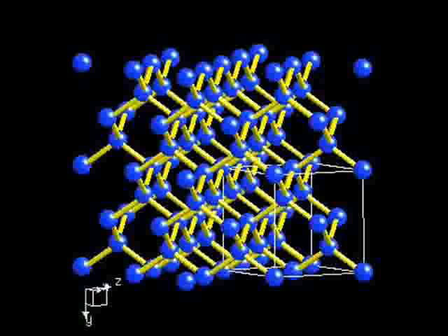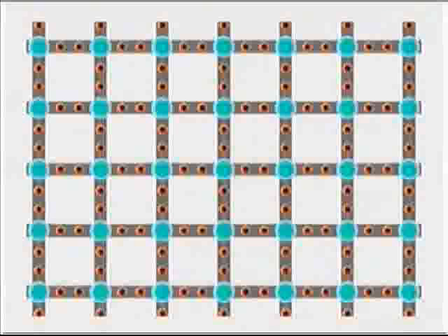In a silicon crystal, each atom bonds with 4 neighboring atoms in a tetrahedral pattern. For our discussion, we will simplify the presentation of the silicon crystal. We will present a 3-dimensional crystal flattened to 2 dimensions. Each silicon atom with its 4 valence electrons shown is bonded to 4 other atoms. If we view our flat crystal along the edge, we see what appears to be a simple row of silicon atoms. Pairs of valence electrons form the covalent bonds between the atoms, and collectively they form the valence band.